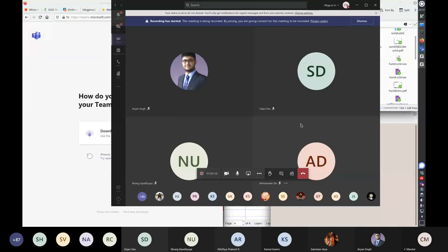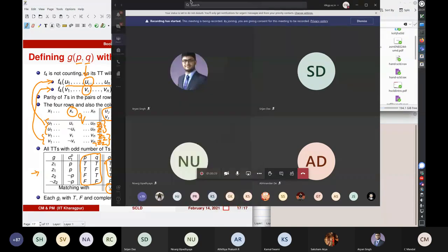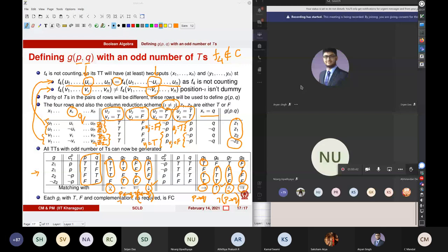Yeah, okay. So that is our treatment on this functional completeness. So what I've seen is that so long as you have these five functions, they don't have to be distinct. For example, you have seen the NAND function. It doesn't belong to any of those classes. So by itself, it is enough. As you have seen, by itself it is functionally complete. You don't need anything else.